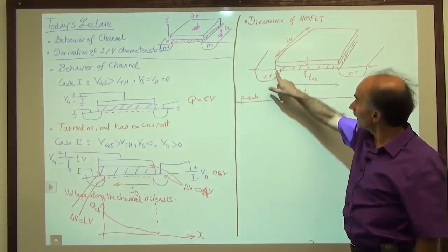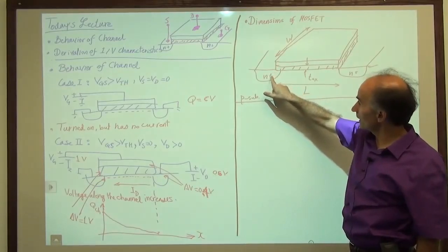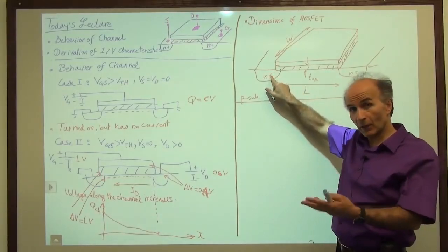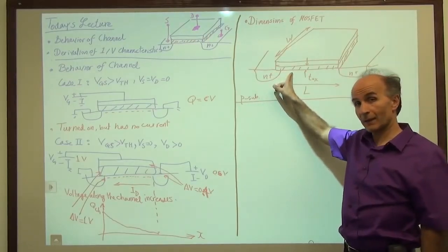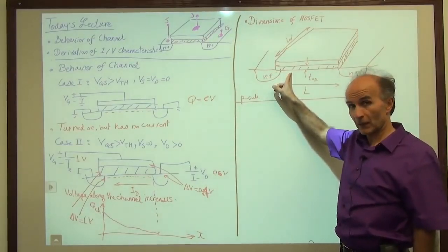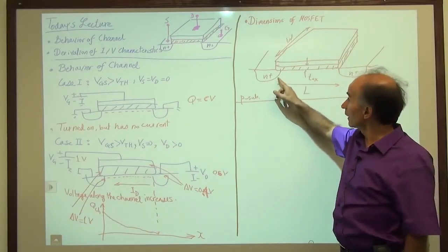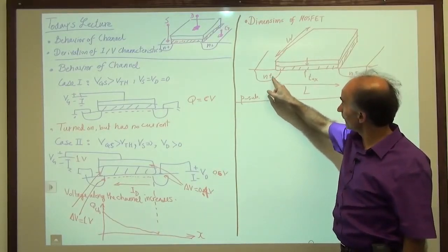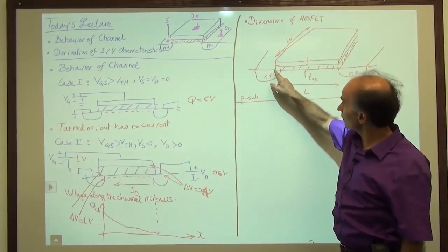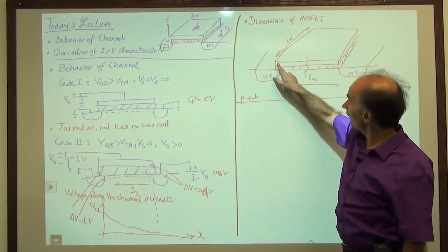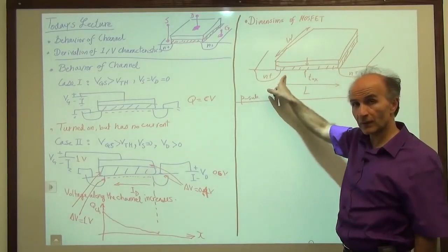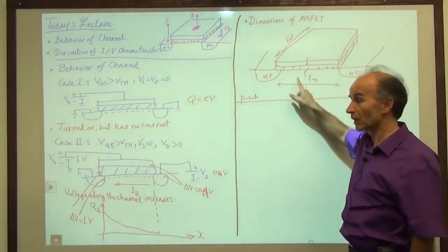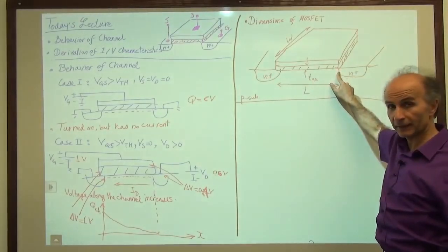During that thermal processing, the dopants partially penetrate this way. We say it diffuses that way. So it's inevitable to have a little bit of overlap between the source area and the gate and oxide area. This protrusion happens during fabrication, and of course similarly on this side.